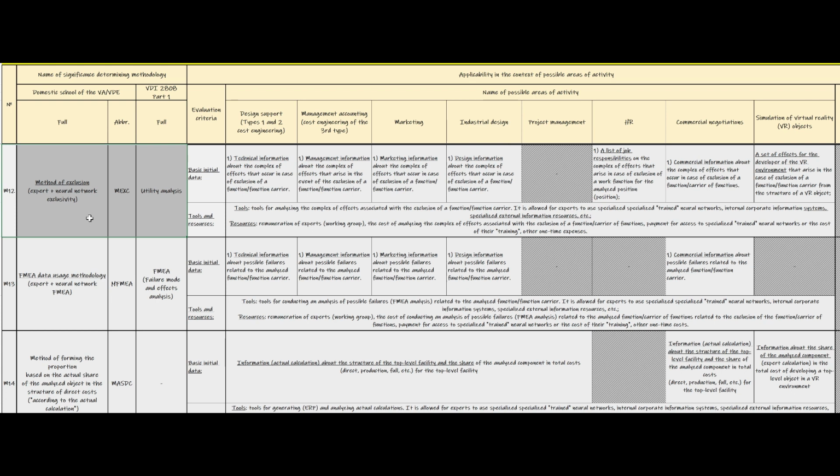If the exclusion effects coincide with the failures described in the FMEA analysis, if there is an FMEA analysis report, the effects can be assigned the appropriate significance values from the FMEA report. In the absence of the FMEA analysis report, as a first approximation, the significance of the effects can be classified as follows.